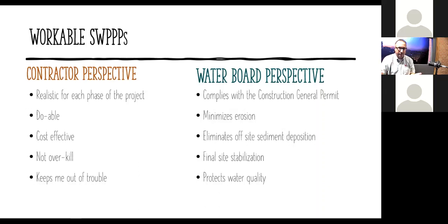And what is our judge of compliance? Well, it's the construction general permit. More specifically, it's based on your risk level. If you're risk level 1, you're going to look at attachment, you probably know it, C, right? Or if you're risk level 2, attachment D, or risk level 3, attachment E. So you're going to take a look at that attachment, those BMPs that are prescribed in that attachment, and that's what the water board is going to judge your site on. If you're risk level 2, they're going to pull out attachment D and say, is it compliant? Is it complying with these minimum mandatory BMPs in attachment D?